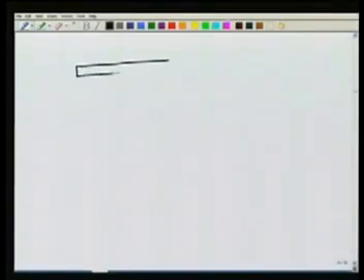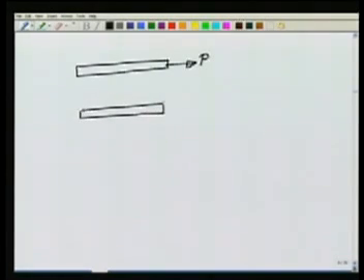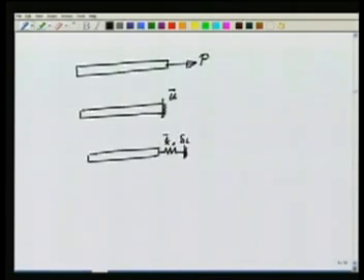So, let us look at the candidate boundary conditions. At an end, let us say a particular end, I can give you a force, I can give you a displacement, it can be built in or some specified value. So, u is specified, or I can give you the force in terms of the displacement, that is, this is a spring with some constant k bar and an initial compression delta L. Okay.